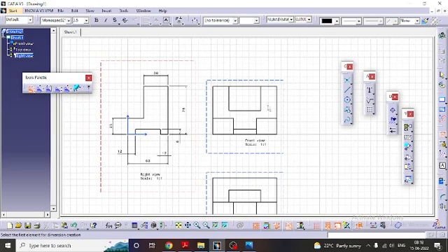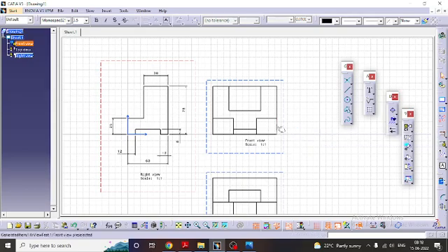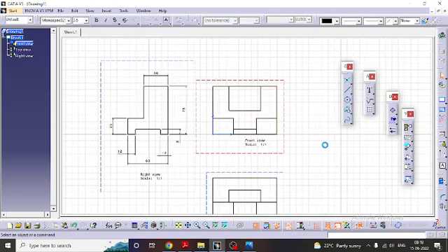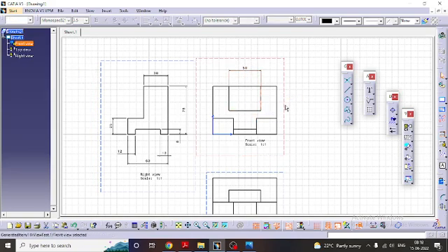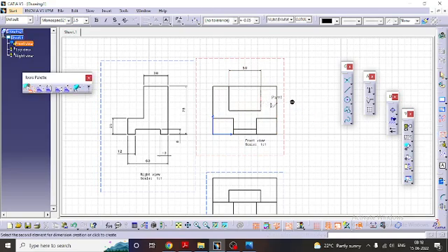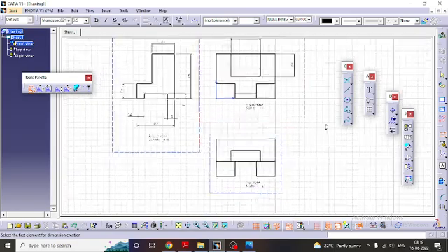Again, for the cutout related things, you have to give it here in this one. Go double click on the front view. So you are making that active for giving the dimensions. Now I'm going to give the dimension as this one and this one, something like this. This is 50, and again from this one is the dimension. Double click on the dimension. This one is 38 now. This is 38, right?